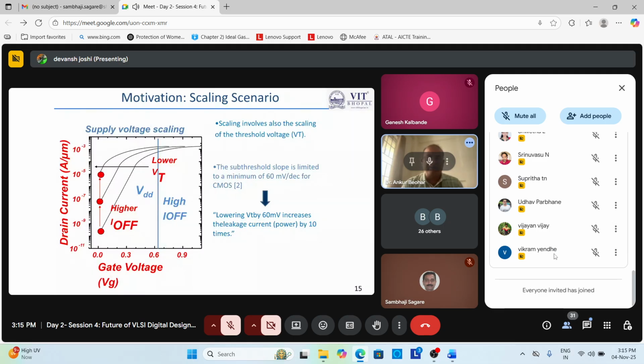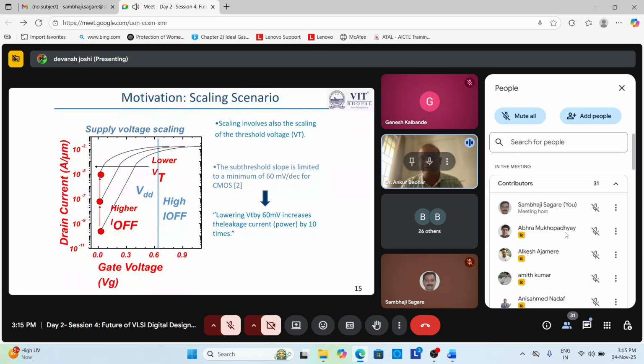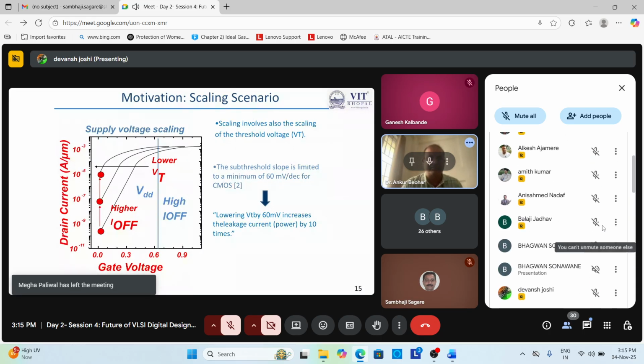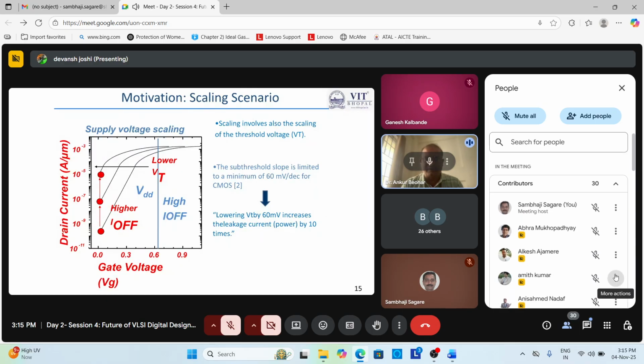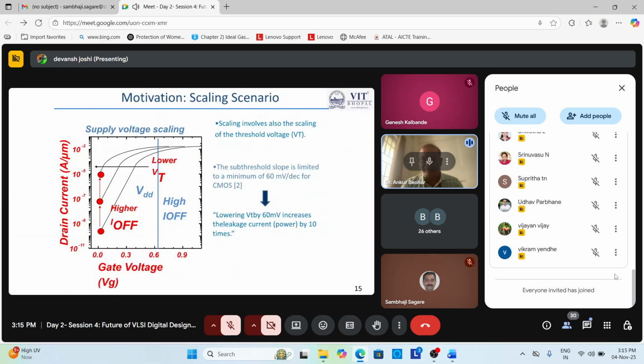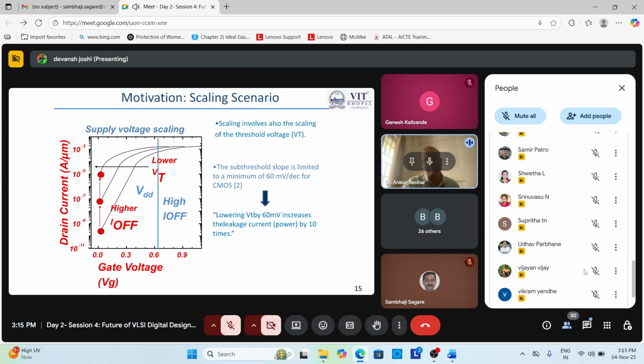But one motivation issue like power dissipation we have already discussed. Same here, we found scaling issues. If we go towards the lower technology node, leakage power is the dominant factor. That is due to scaling, and with a high drain voltage, some short channel effects arise. You can see the MOSFET subthreshold slope term. Basically, subthreshold swing is one of the degrading properties of any device, so it should be as low as possible. But in the case of MOSFET, it is limited to 60 millivolt per decade.